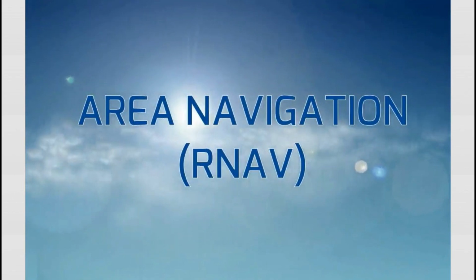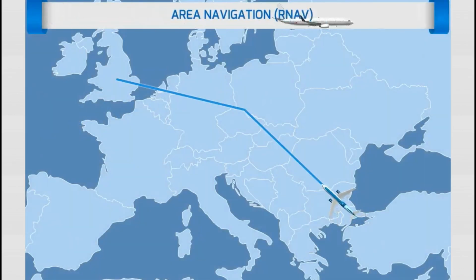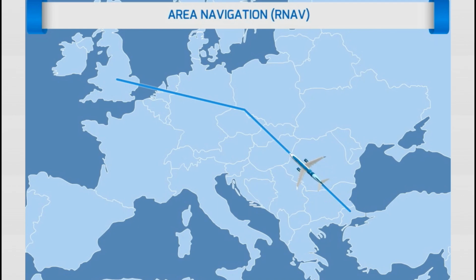Area navigation, RNAV, is a method of navigation that permits aircraft operation on any desired course within the coverage of station-referenced navigational signals, or within the limits of a self-contained system capability, or a combination of the above. This is accomplished primarily with navigation referenced to GPS. In addition, the Flight Management System, FMS, will also auto-tune VORs, DMEs, and compare any additional navigation sources like IRUs, TACANs, ADFs, and LORAN-Cs that might be on board to increase the precision of navigation.